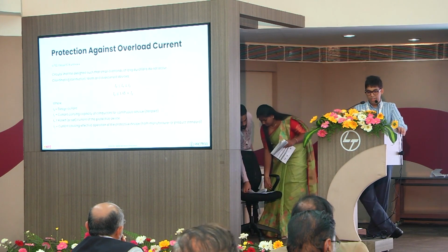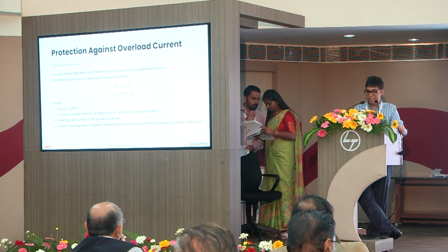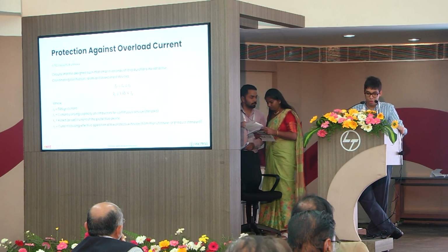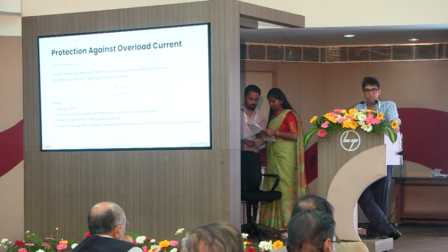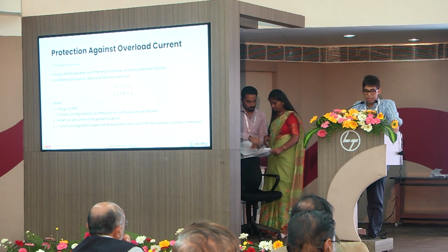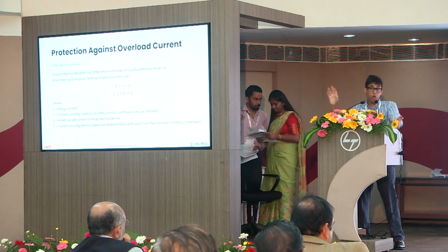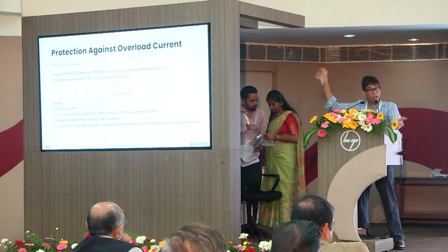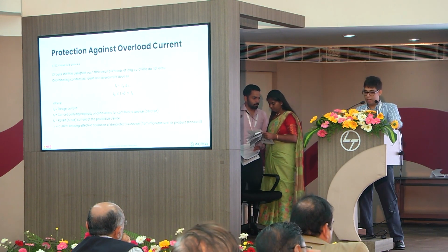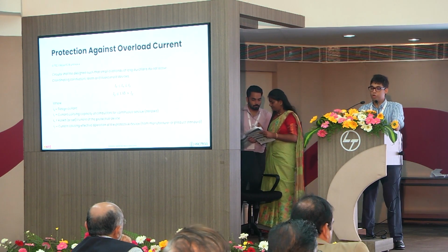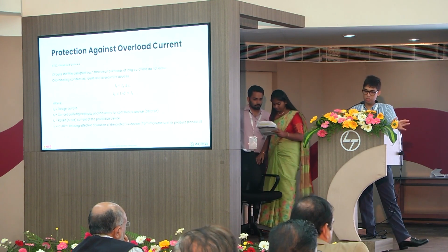Then this is a very important thing which is not exactly talked about a lot. I think Mr. Appavu had made a very interesting spreadsheet for this, which is why I delved into this deeper and started talking to people about it. See, there is something called I2, which is defined in all the product standards for overcurrent protected devices. This is the current the circuit breaker will trip at in a given time for overload. We're not talking about your RCDs, overcurrent, short circuit or fault trippings. We're talking about what the circuit breaker will trip at in an overload. This value has to be lesser than or equal to 1.45 times IZ. And IZ is the current carrying capacity of the conductor for continuous service, which is derated.